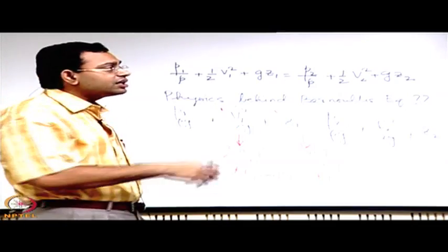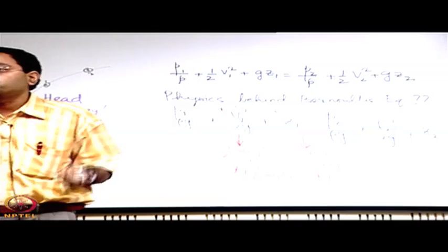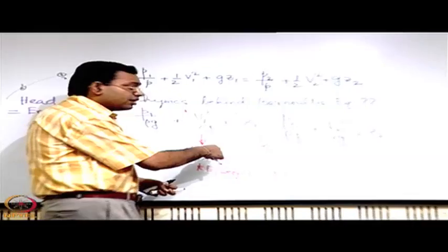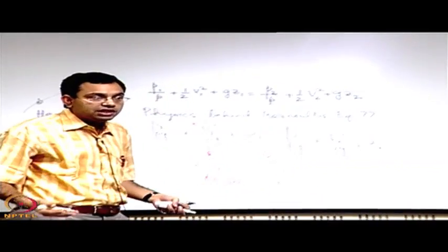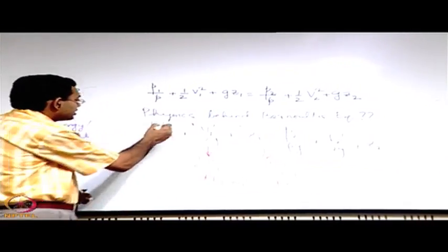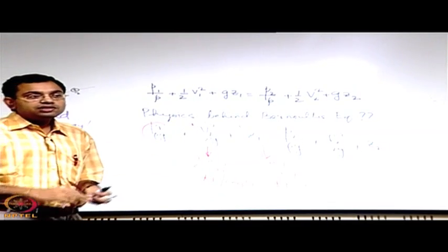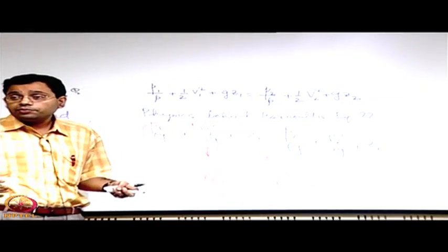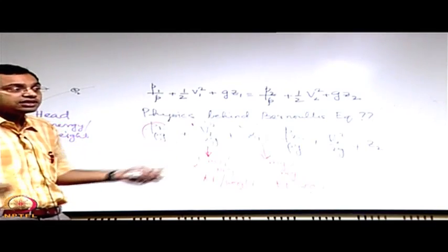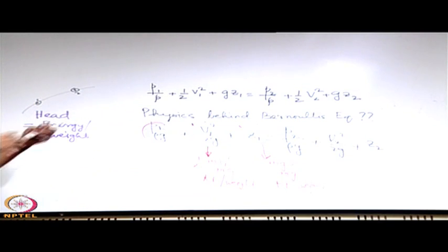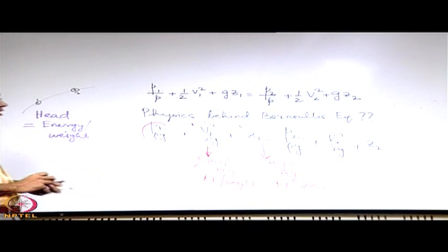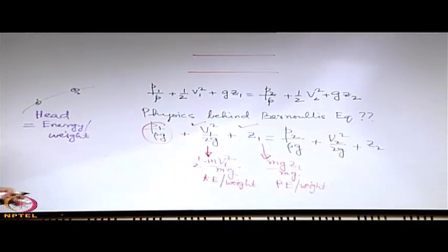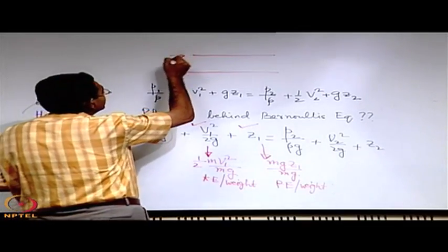So, let us try to see what that terminology is. Maybe terminology is not so important, we may use some other term also for that, but what does it physically represent? We can understand the kinetic energy and potential energy, what these physically represent, but what this physically represents is not very straightforward from this, and if we want to make it very straightforward by calling it pressure energy, perhaps we are trying to suppress our lack of understanding of it. So, let us not do that, let us expose our lack of understanding and see what it should be. So, let us say that you have a pipe and fluid is trying to enter the pipe.